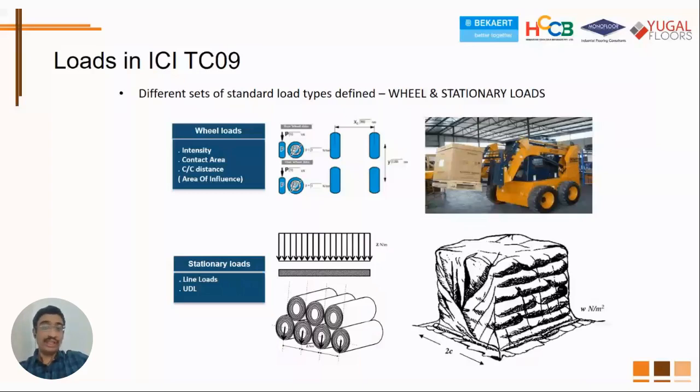And then you could have UDLs. Of course, UDLs are possible, but then only in this condition where you actually are looking at some stack of bulk material like this. And I would like to point it out to you: just try to recall in your projects, if at all you really had a UDL like this in your floor. That would tell you where we are placed with regards to UDL and how we take this as input in our designs.